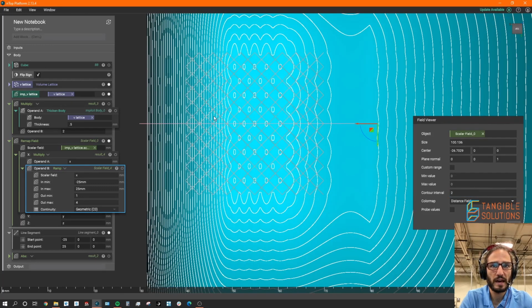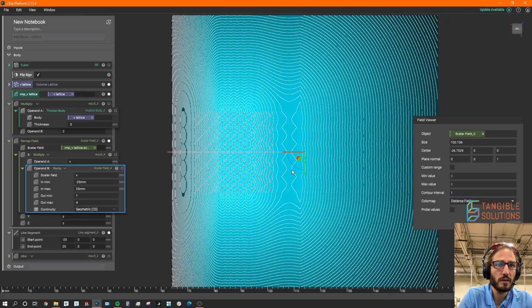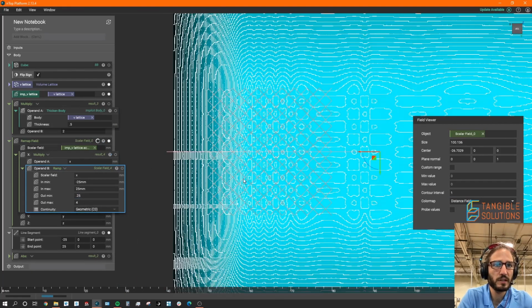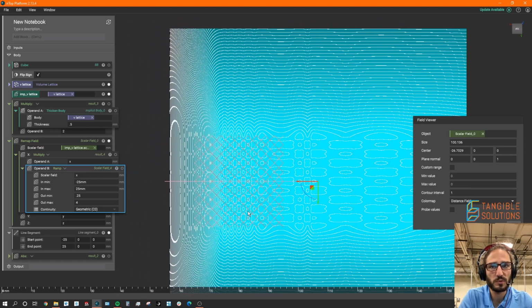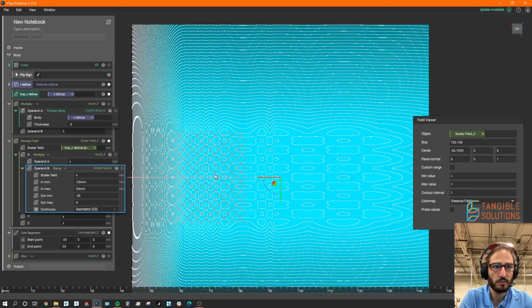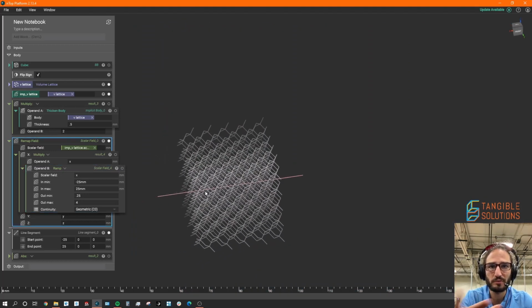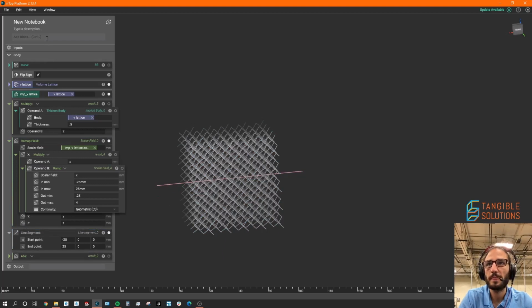Here in our lattice region, you can see this is where the start of each of our beams are. And as we get a little bit bigger, let's actually turn that back to 0.25. As we get a little bit bigger, you'll notice here that we get some pretty crazy stretching. And you'll see what that does once we start to take our lattice and we want to be able to thicken it. So I have this remap field. What I'm trying to do is change the cellular spacing.